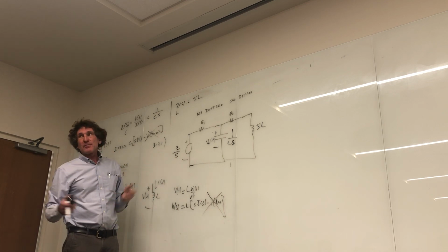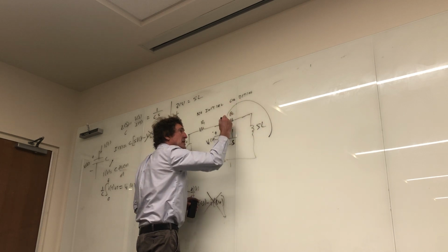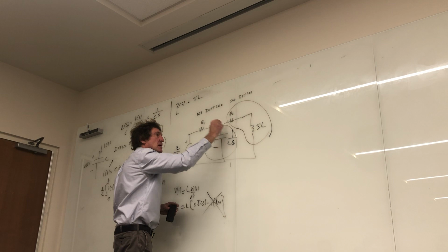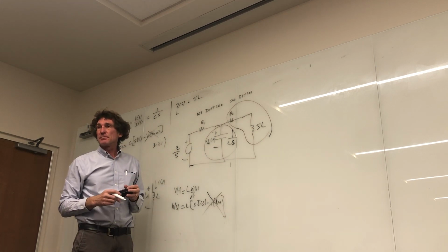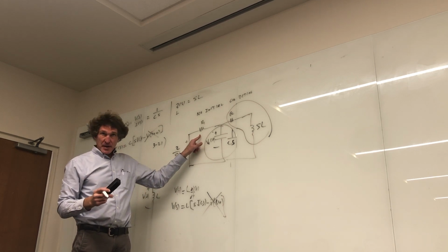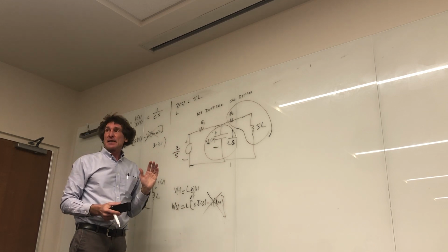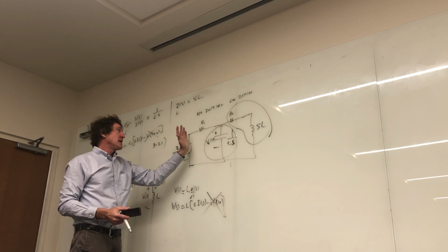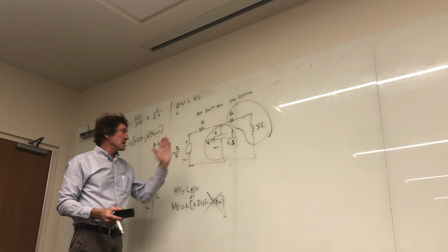You can do it probably the way a lot of you would do it, I'm guessing. You would say, well, this is one block impedance here, and this is a block impedance here. So they're in parallel, right? So I could get the effective impedance of those two in parallel. Are you with me? Then I could add this R to it, agreed? Then once I have that, I have the net impedance that this voltage source is seeing. And then I could get the current coming from here, which would be this voltage source divided by the impedance looking in.